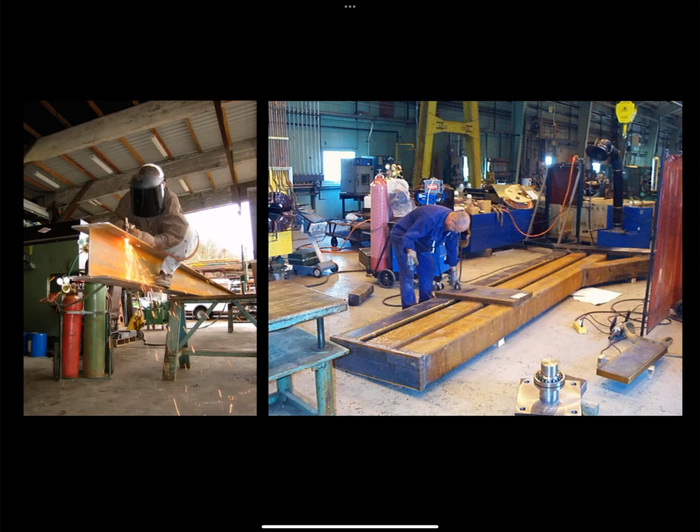So when we design a steel structure, your structural engineer will do a set of drawings of the steel frame structure. And then those drawings go to the steel fabricators, who will in turn do a set of shop drawings. And the shop drawings are the fabrication drawings. They're much more detailed. They show every hole, every bolt, every plate that gets welded in, all of the profiles of the welds. Every single detail is drawn and specified.